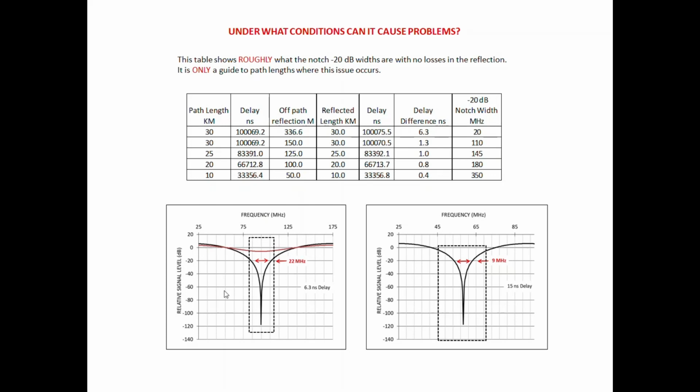The dashed line here is a channel bandwidth of 30 megahertz. I used that because I was working with 6 gigahertz case when I did this plot. So basically the channel bandwidth is very close to 30 megahertz, and it's shown here. Now I should point out, of course, that this pattern is pretty much band independent. The width of the notches and the channels and so on is related much more to the time delays and the reflection losses, and it's not affected by the actual band.